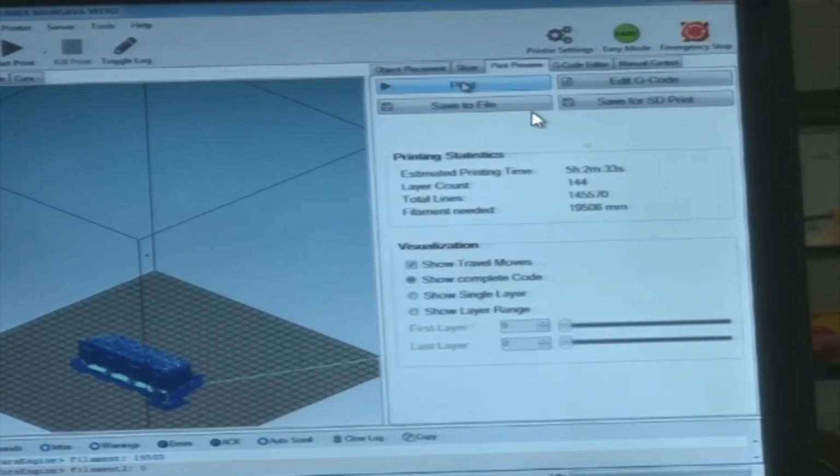Now there is another way. If we go to the print button here and click print, all these manual controls that we have set manually will be enabled automatically, because the bed has to be heated, the nozzle has to be heated, and the fan has to be kept on. All the settings that we made before would be activated by just clicking this button. So this is the automated mode.